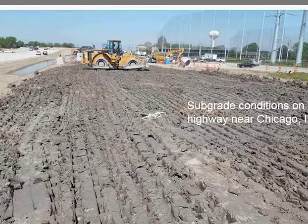And the contractor came up with a fantastic idea to improve compaction, which was instead of just rolling it in the longitudinal direction, to roll it in the transverse direction. And that had no effect on improving compaction, okay? But it was something that the contractor was trying to do to make things better.